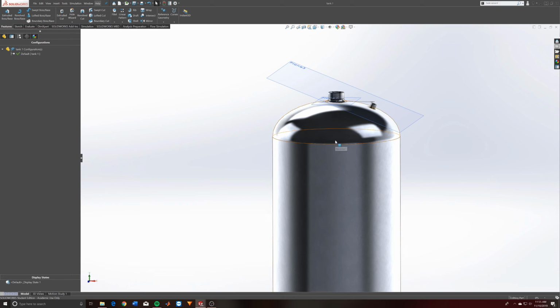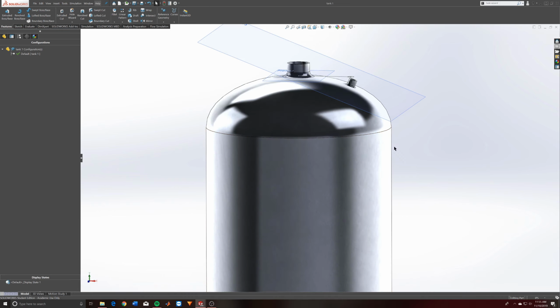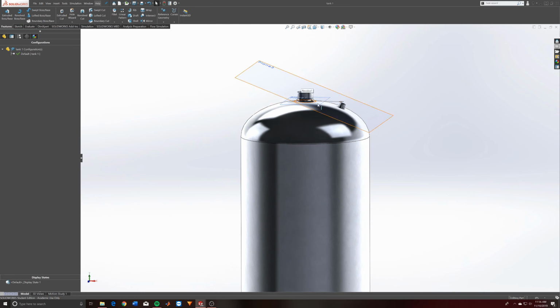Because you'll see that singular parts that are all together will usually withstand more force than an assembly will. So keep that in mind, but usually a part is a really good way to get started and get a general idea. Since what we want to do is determine the thickness of the wall for a certain amount of pressure, this should be fine. I'll show you an assembly FEA of this kind of stuff later on, especially once we get into adding the flanges and the piping. From there we'll be able to see much more about how to run FEA for multi-part assemblies.